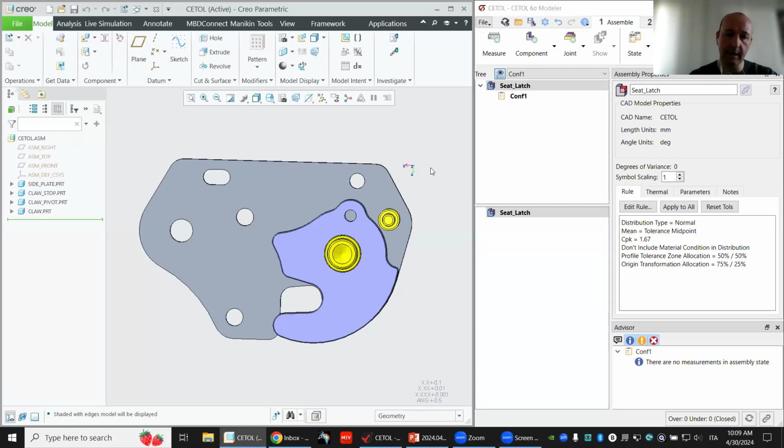And for design, I mean three-dimensional nominal CAD model and the dimensioning schemes present inside the technical drawings. And we can see which are the best corrective actions that we can apply from the tolerance point of view to obtain at the same time a robust design from the tolerance point of view with the higher value for the tolerances possible in this case.